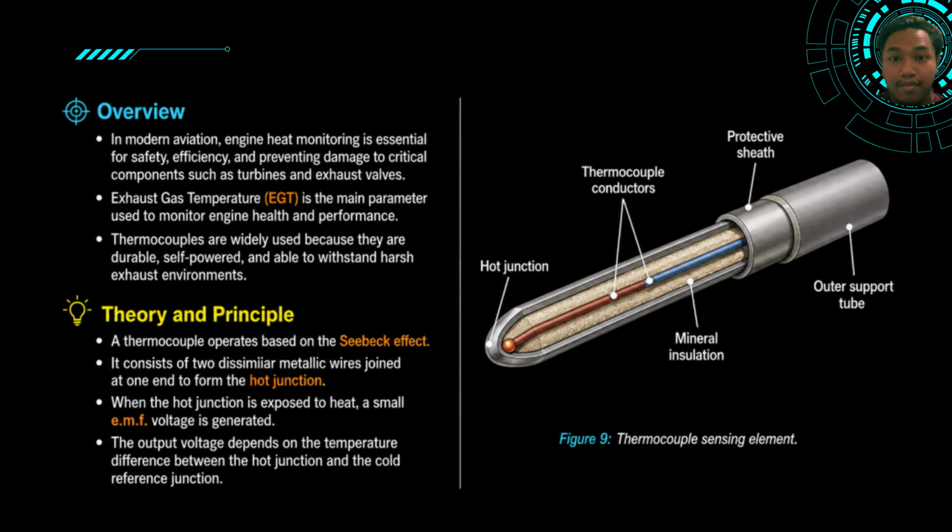Today I will be discussing thermocouples, or heat sensors, in engine heat measurement. As you can see, monitoring exhaust gas temperature, or EGT, is absolutely essential in modern aviation for safety and preventing turbine damage. We rely on thermocouples for this task because they are remarkably rugged, self-powered, and can easily withstand the extreme engine exhaust environment.